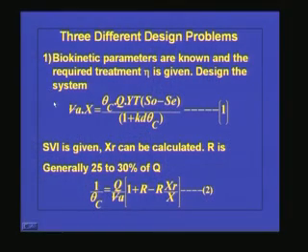So this expression we have already seen: theta C equal to this expression, or we can change the expression the other way, VA, that means the volume of the aeration tank, into the concentration of the biomass, is equal to theta C, this is the biological sludge retention time, into flow rate into yield coefficient into initial BOD minus final BOD, divided by 1 plus the decay constant and this is the BSRT again.